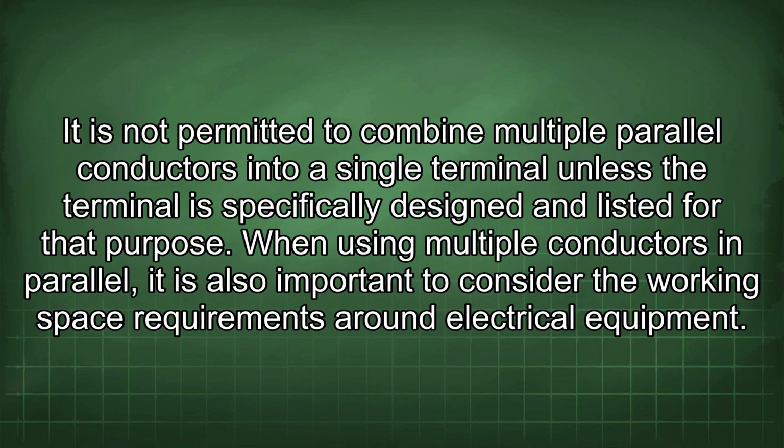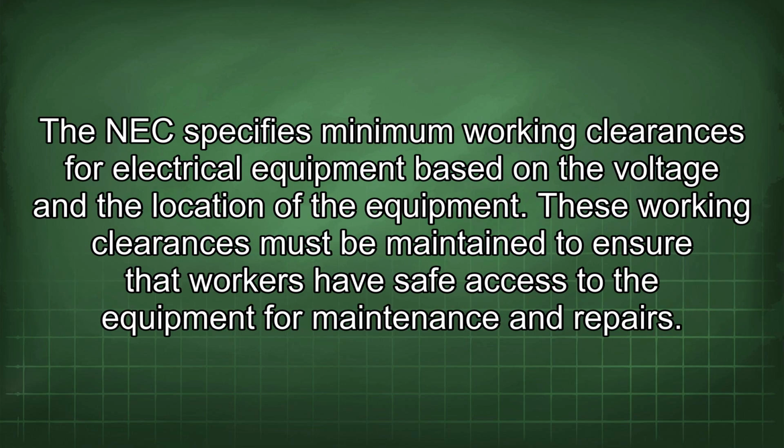It is not permitted to combine multiple parallel conductors into a single terminal unless the terminal is specifically designed and listed for that purpose. When using multiple conductors in parallel, it is also important to consider the working space requirements around the electrical equipment. The NEC specifies minimum working clearances for electrical equipment based on the voltage and the location of the equipment.